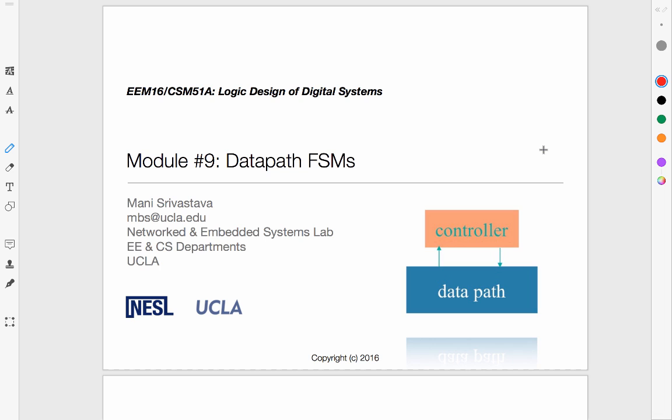Now, the way you would do it is the following. Unfortunately, commercial tools to work with FPGAs are quite a bit of a pain, partly because of licensing reasons and all. And they don't work on Macs, which many of you have. So what we have done is we have figured out an entirely open source design process. The only bad part is it works under Linux. So we'll have a Linux server. You submit a file, it will give you the design, and then you can download it to the FPGA. So that's how it's going to work.